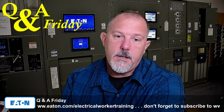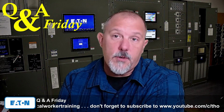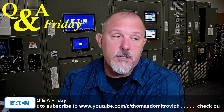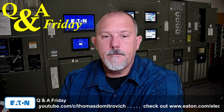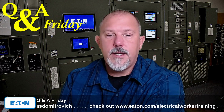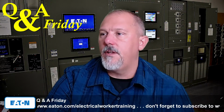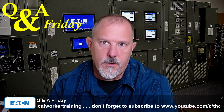and some of those you just can't throw a fuse in front of. And I would argue that even if you had a 10K GFCI receptacle, it was tested and it achieved its 10K short circuit current rating when you have a fuse in front of it, and you rarely see any of those installed downstream of a fuse. So the whole aspect of short circuit current ratings and evaluation with a fault current is challenging.